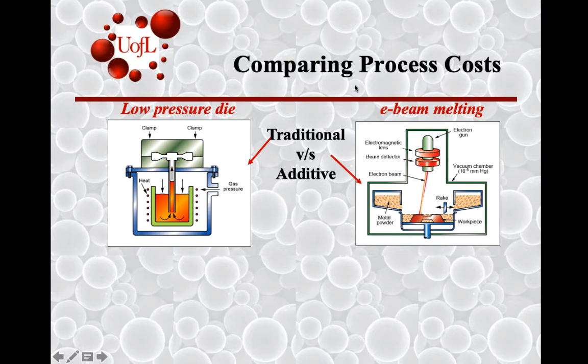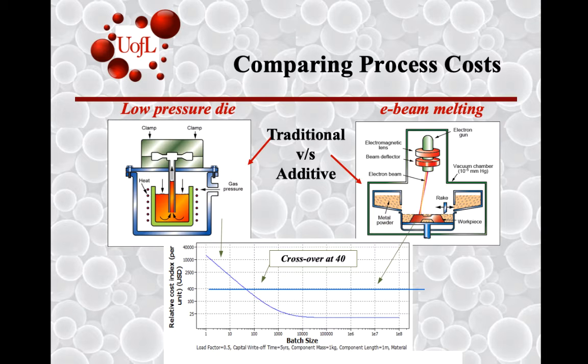One specific example is electron beam melting, where you go directly from a CAD file, raster an electron beam through slices of these parts, and build them up from a powder bed. In that case, you don't have a tooling cost because these are die-less fabrications of the same parts. So in those cases, typically you will have this relative cost index be relatively invariant over production batch size.